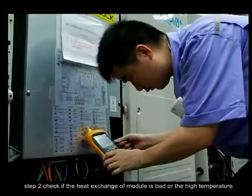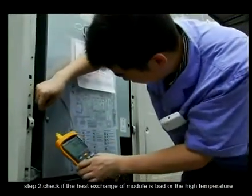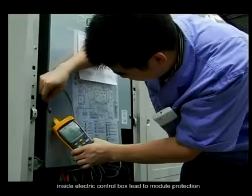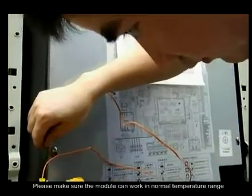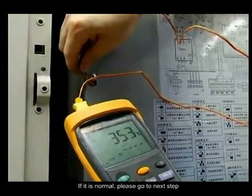Step 2. Check if the heat exchange of the module is bad or the high temperature inside the electric control box leads to module protection. Please make sure the module can work in the normal temperature range. If it is normal, please go to the next step.